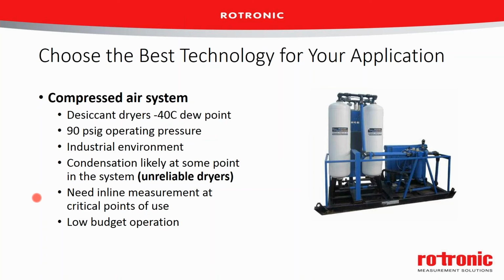Aluminum oxide, because of the condensation, we're going to remove that one. And also, typically, aluminum oxides are not inline. They do take a sample. And the other critical point is, as I just mentioned, condensation. Aluminum oxide doesn't like condensation, and that leads us to choose the capacitive sensor. So a modified capacitive sensor, and it's very important to get one that is modified so it can detect accurately low dew points. And that's how we would go through that selection process.